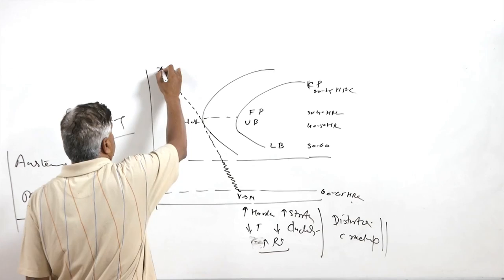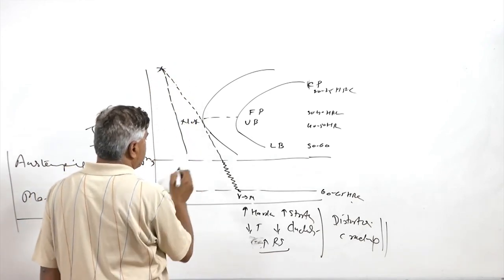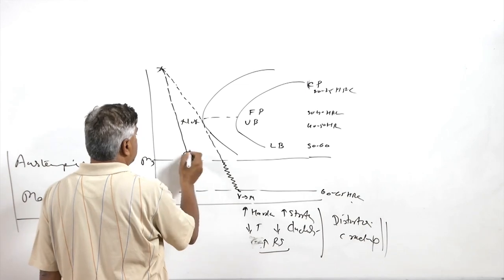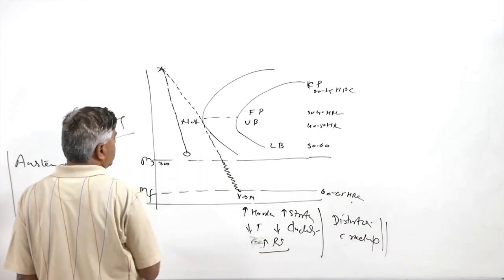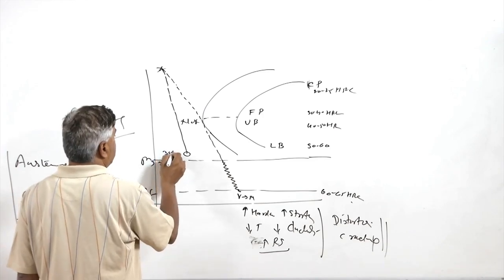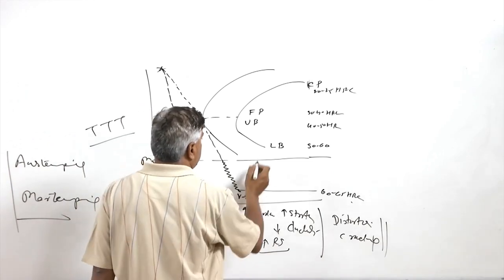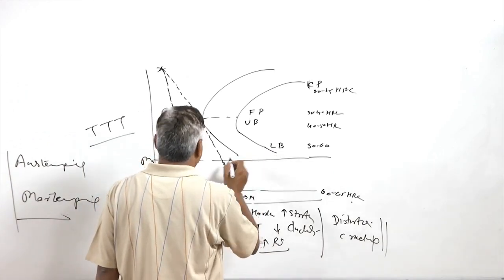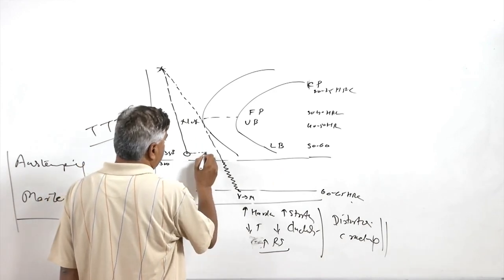is quenched from the homogeneous austenitic state to a temperature just above the MS temperature. So say if MS temperature is 300 degrees centigrade, then at 350 degrees centigrade a bath is kept and the sample is quenched in the bath kept above the MS temperature, and then it is held for sufficient time.